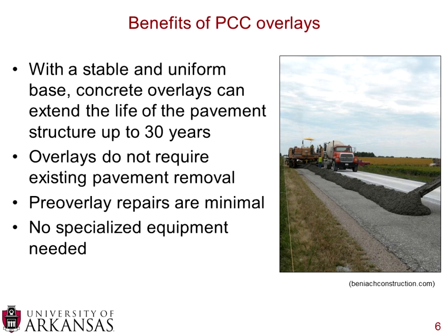So a typical paving train, like a screed and the concrete trucks, is the same equipment that you'd use for a traditional Portland cement concrete job. You can see over there on the right the picture. They're placing new concrete along a little windrow there, and that concrete truck in the center of the picture, not the one delivering the concrete, but the one in the other lane, that's actually traveling on a thin overlay. And if you look closely right under where the fresh concrete is being delivered, you can see that concrete overlay. It's about 3-4 inches thick. So these are often a little thinner than your traditional concrete pavements.